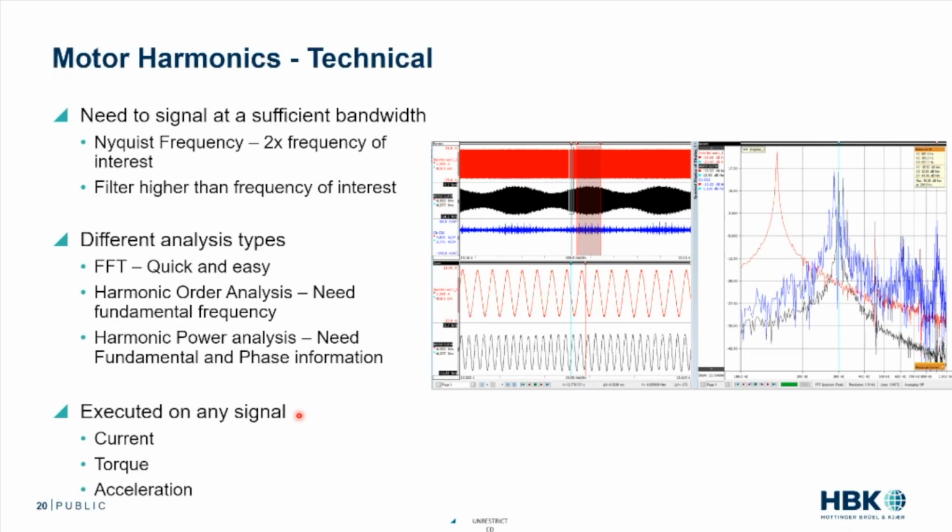All of these techniques can be executed on any signal: current, torque, acceleration, microphones, vibration. Order analysis is really key to things like vibration and noise. And I'm sure there's a lot of NVH engineers in here falling asleep with my basic overview, but I think we'll forget the basics quite a bit.